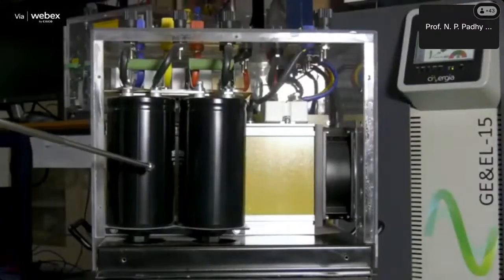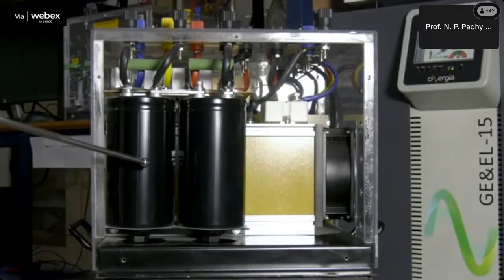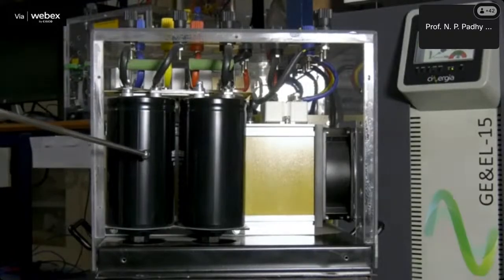One important thing to be noticed here is that the DC input capacitor or the DC bus should be rated to more than peak of the grid voltage such that the power can be transferred from the DC side to the AC side. The basic understanding here is that unless you create a voltage difference, it is not possible to transfer a reasonable amount of power from one point to the other.